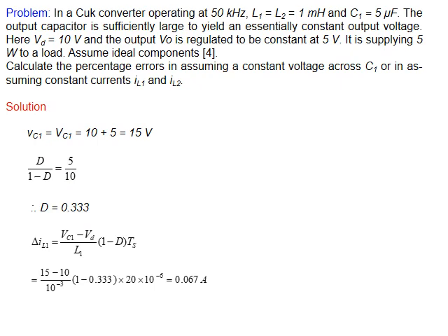Now, let's take an example on the Cuk converter. Before I continue with the example, just to let you know that we usually assume the capacitor is sufficiently large and has constant voltage, and the current in the inductance is constant current. It means the current is increasing in this way, decreasing in this way, with no curve, just a straight line. Okay, now back to the example.